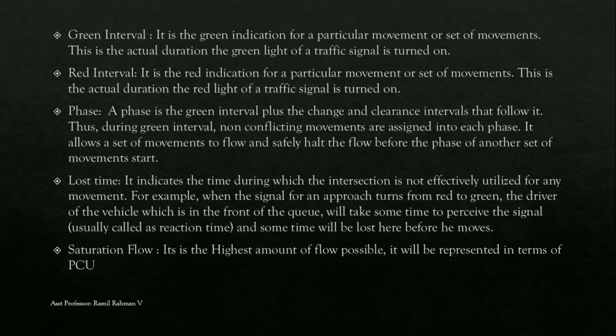Lost time. It indicates the time during which the intersection is not effectively utilized for any movement. For example, when the signal for an approach turns from red to green, the driver of the vehicle at the front of the queue will take some time to perceive the signal, usually called reaction time, and some time will be lost before he moves. The next term is saturation flow. It is the highest amount of flow possible, and it is represented in terms of PCU.